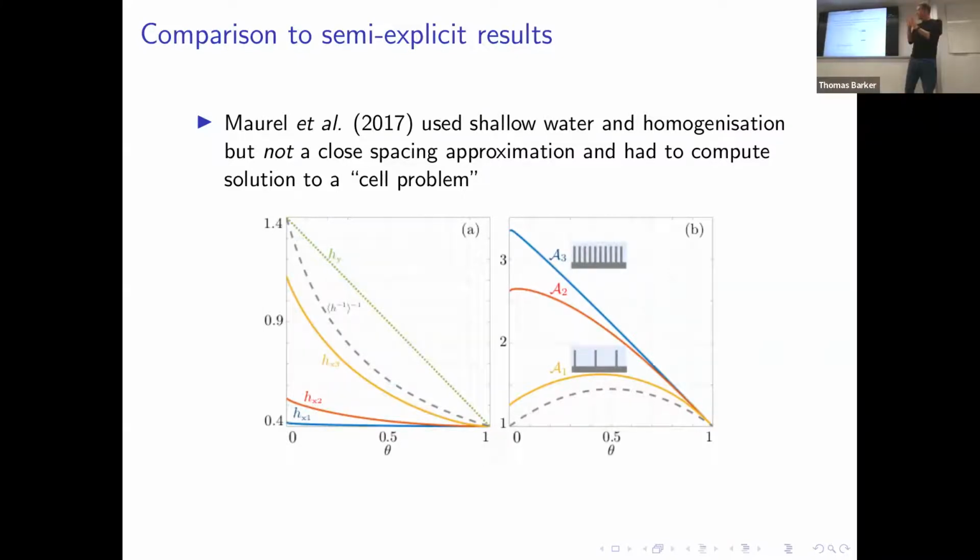I've got these plates very, very close together so that the waves running over the top just feel the tops of these. The fluid flow doesn't have a chance to dip into each of these cavities here. Okay, and so my predictions of this green line will coincide with this green line and with this horizontal coordinate. So they match up with other people's simulations. So mine is explicit, and these are numerical computations that have to be done.